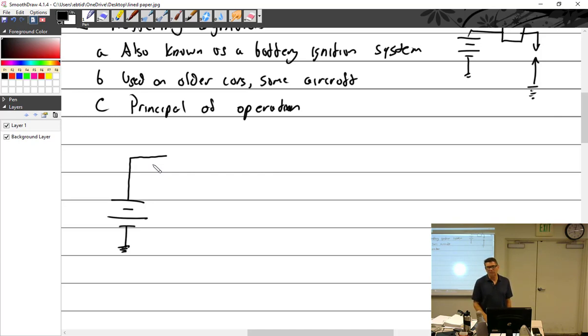So now we have this new technology. In fact, we were just talking the other day, I didn't realize that they make an STC, at least for your airplane, where you can take it all off and put on two Surefly or electronic ignitions. A different company, so there are different companies. But you can now put on two electronic ignitions, but you have to have a redundant battery, a second battery, and wiring. In your airplane, you still have an electronic and an analog? Yes, right now one Slick, or a Bendix or a Slick, and then the other one electronic.